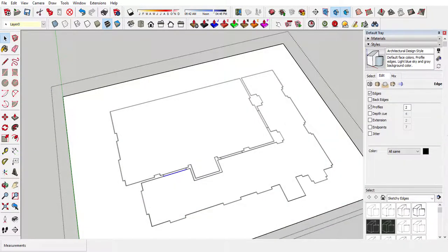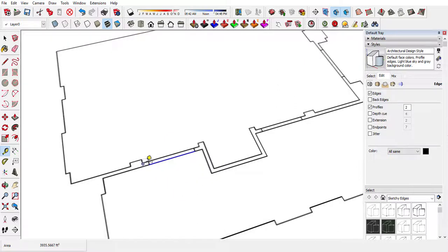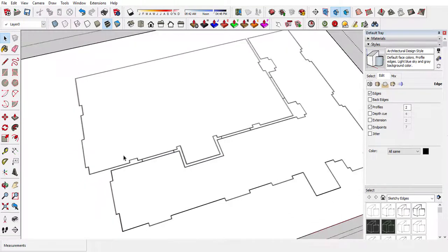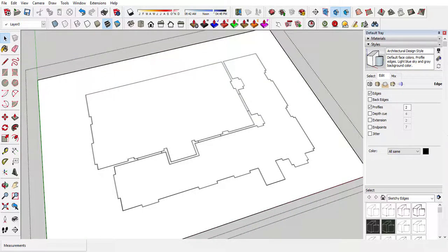After the object is to scale, I always like to use the tape measure tool and just verify that indeed this is 6 foot long, and sure enough, it is. At this point, I'm going to delete this line because it could become a problem later on. So just select it somehow and hit the delete button. We don't need to worry about the measurement. We figured it out. It's 6 foot. We can now start building up on top of this image.